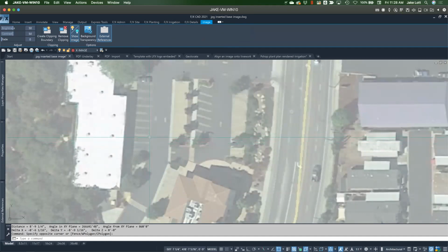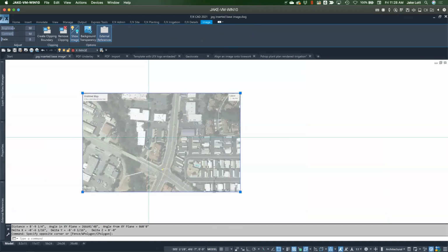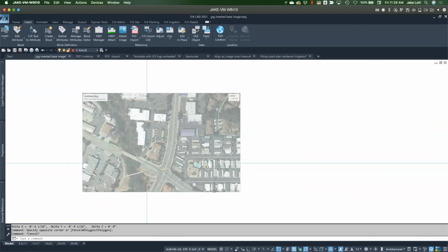If we're off by just a couple inches here, that really extrapolates across the site. So we might be off in a larger grand scheme number versus taking a larger distance to scale from. So just keep that in mind as you're scaling things, that as best as you can, use a large portion of the site to be able to scale. But this is now scaled, and we can technically start working on it and doing whatever we need to do.